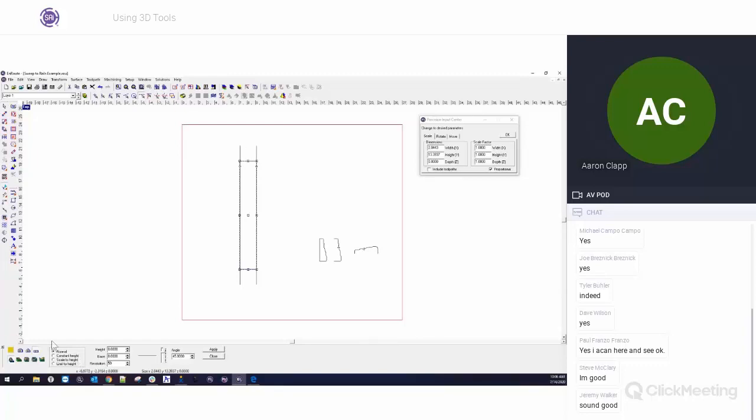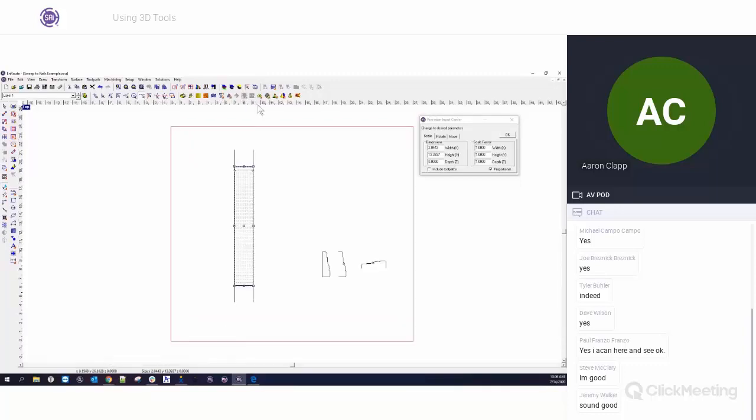So I'm going to select this rectangle. I'm going to say create relief, or go to surface, create relief. I'm going to say add flat, and I'm going to put 0 and 0 for the base and the height, because all I want is just a starting point, a flat, no thickness relief. And we kind of talked about that last time. Hit apply. This gives me a flat, no thickness relief for me to be able to use the tool.